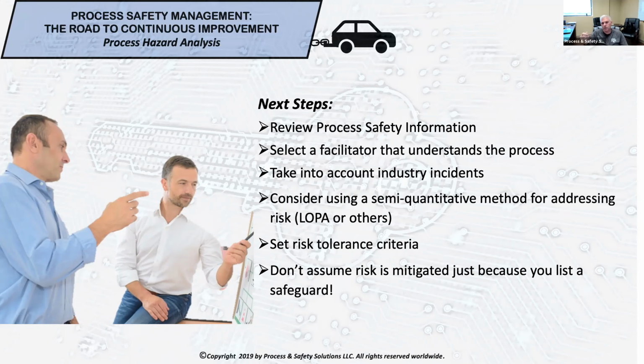And two, do we have the testing and inspection records for that safeguard? And is it operating in the way that we said it was operating, and we've documented that somewhere? If we don't have that information, then maybe it's time to go back and say, let's redo this PHA with that information corrected and brought up to date.